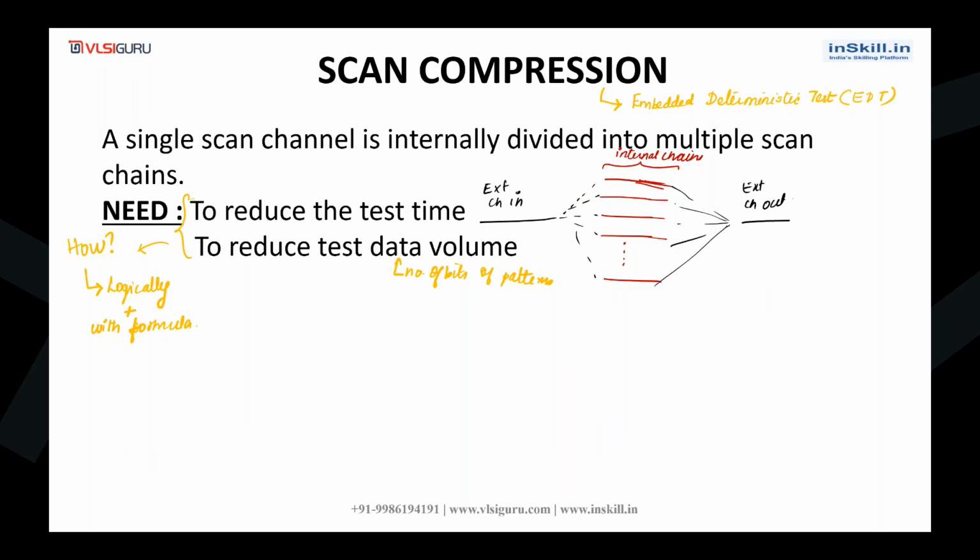If you want to achieve scan compression, if you are using Mentor Graphics tools, you need to add up a logic which is embedded deterministic test, EDT logic.